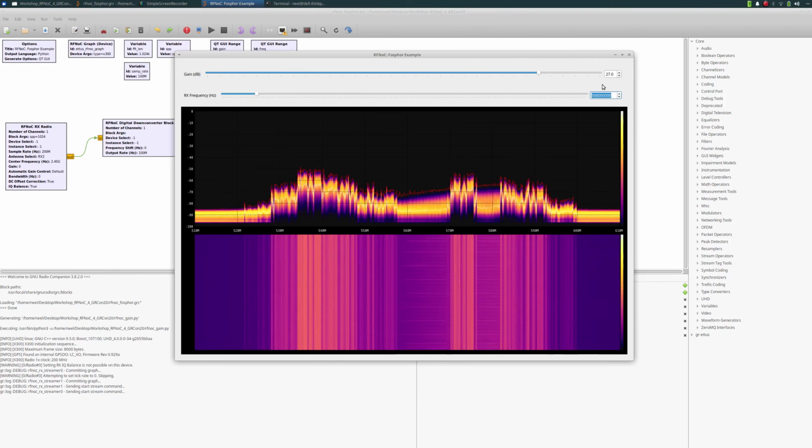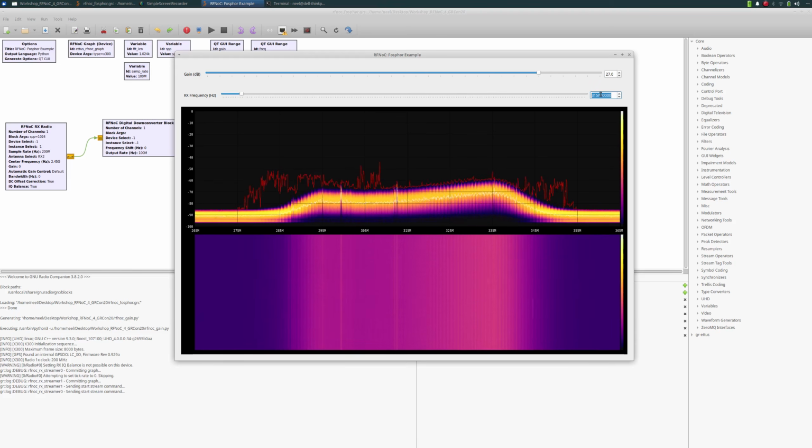Next, let's tune to 315 MHz. Most remote key fobs for cars operate at either around 315 MHz or 434 MHz. I've seen a few also operating in the 915 ISM band. You can always check the FCC ID of your key fob to determine what frequency it operates at. The FCC ID for the key fob for my Honda reports a frequency of 313.85 MHz.